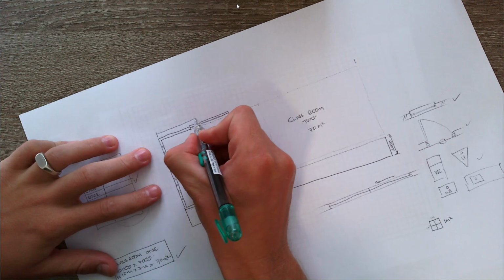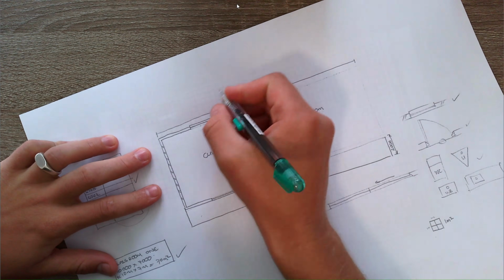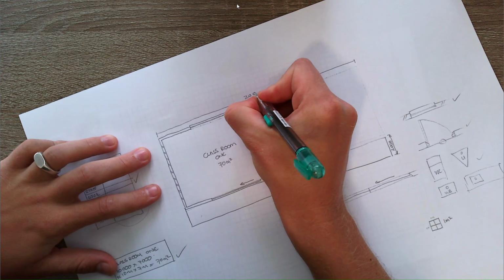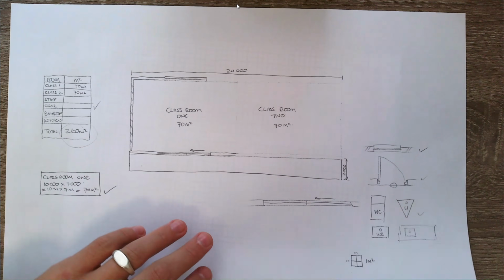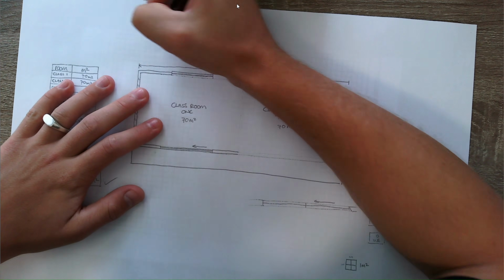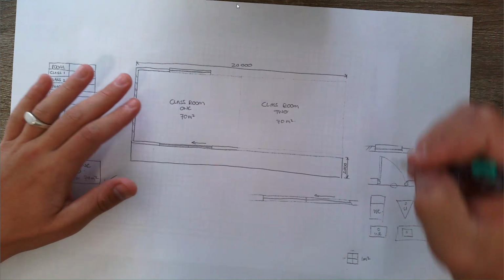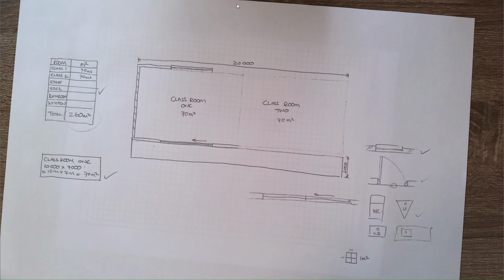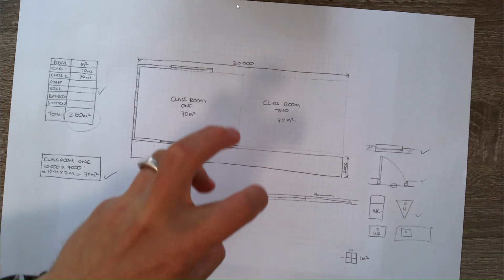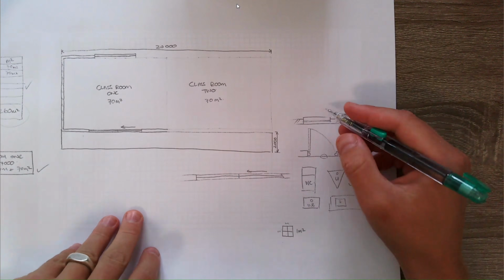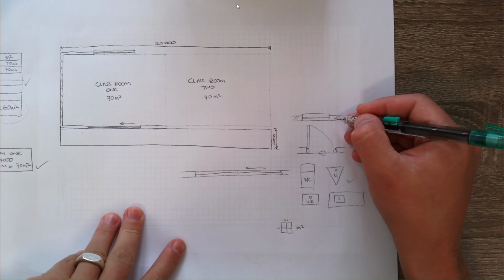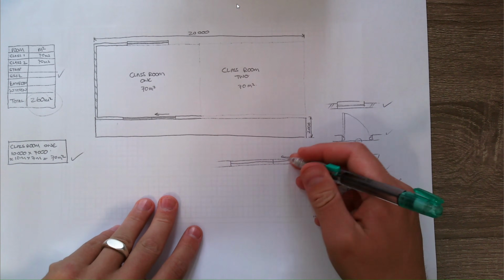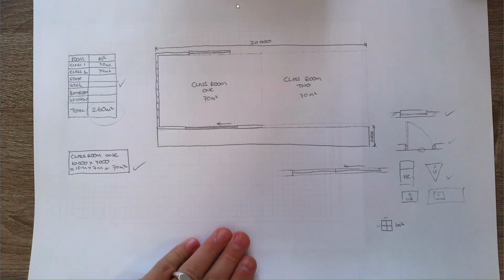You can then say that this total is 20,000. You can use your blocks as guidance because you know one block is half a meter. So you need to give dimensions, you need to give your labels. Remember, this is just an example to show you what you should do when it comes to the features and how you should show your windows, your doors, the sliding doors, and the calculations.